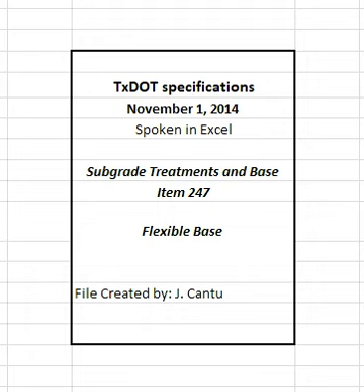2.1.3.2.1 Contractor furnished recycled materials. Provide recycled materials, other than RAP, that have a maximum sulfate content of 3000 ppm when tested in accordance with TEX 145E. When the contractor furnishes the recycled materials, including crushed concrete, the final product will be subject to the requirements of Table 1 for the grade specified.